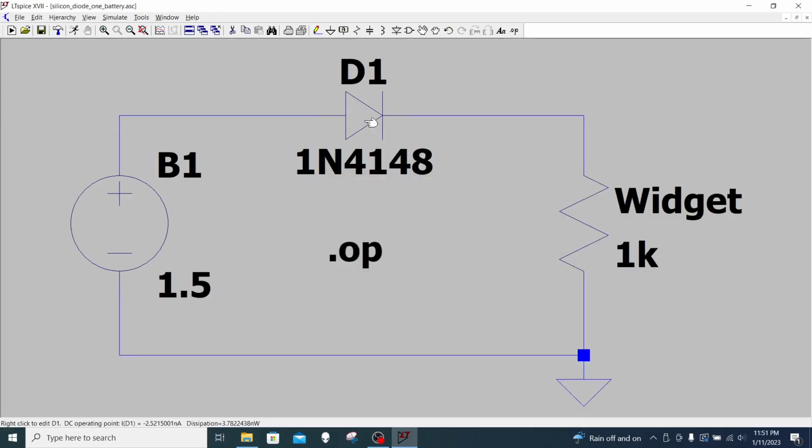Let's see what we can do if we replace that diode with a Schottky diode. Generally speaking, they're going to have a much lower forward drop than a silicon diode. The downside is often you may have to settle for a lower peak reverse voltage. Also, there may be significant reverse leakage current in that reverse battery case, and we'll look at that in a second.